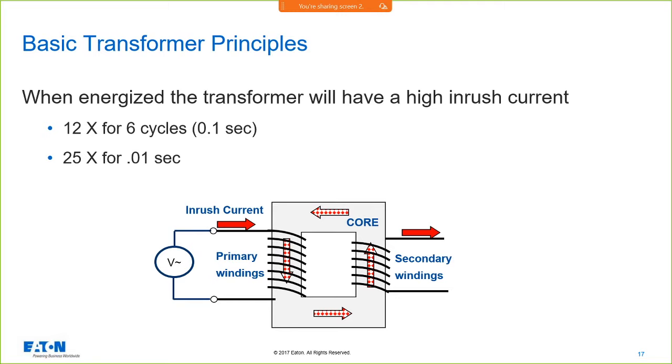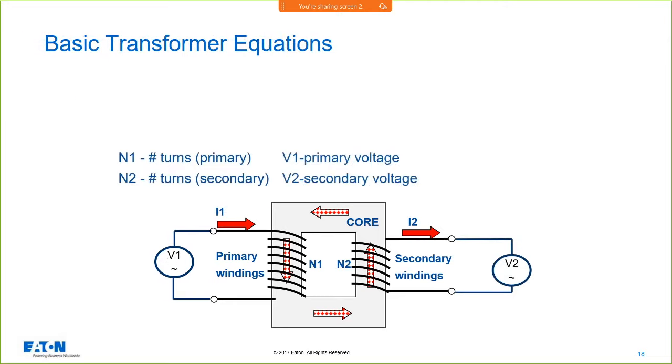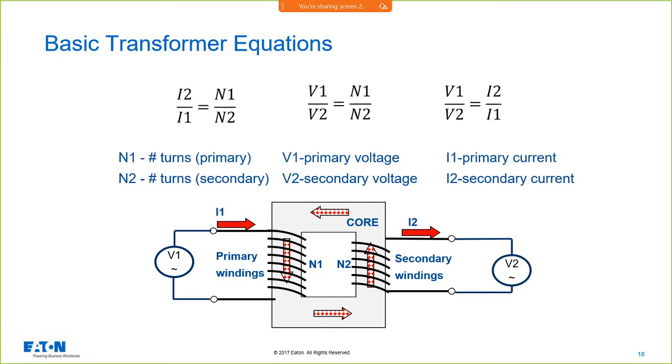I'm going to have an inrush current when I apply that voltage. That is based on the characteristics of the windings and the core, et cetera. I have to deal with that inrush current, like a motor's inrush current. Anytime you deal with coils of wire around iron cores, when you start energizing that, it's going to create a challenge for you with regard to that inrush.